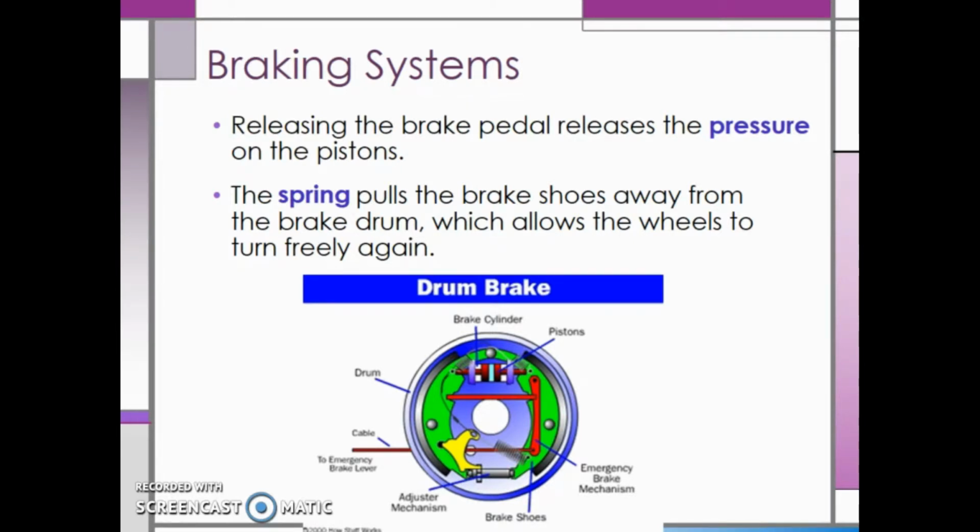When you push the brake, each piston will expand on each side of a drum brake, which basically pivots around the bottom or the hinge, so they push out on the top. This means all of the wear of a drum brake is on the top.